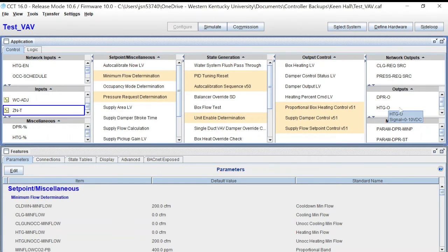Another thing that you need to be paying attention to is the direction of those outputs. For example, once you get your system up and running, if the damper is mechanically set the way that it needs to be, now depending on how a VAV mounts, your damper may need to rotate clockwise or counterclockwise for a particular position.